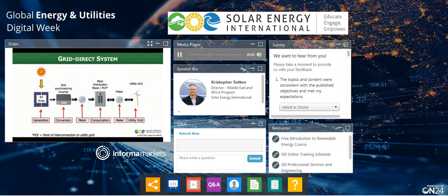Bidirectional really means that it's been calibrated and tested to run both directions and measure accurately in both directions. So that's our bidirectional utility meter. And that's often what we would call a net meter too, because it just sees the net difference between import and export. Now, the other thing about this type of system is that it assumes that the utility grid will allow us to push power back into it.